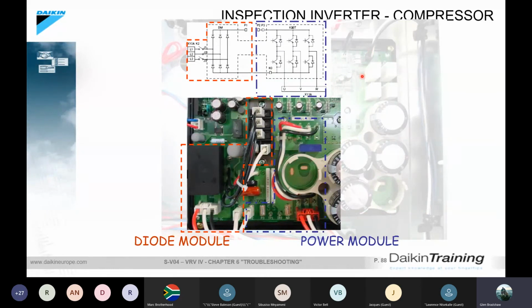Now, the only way that you can effectively change the speed of a motor is by playing with the frequency. And I think if you go back to the old days of standard compressors, many of you may have remembered that you could often select replacement compressors from Tecumseh and things like that, and you would see a chart for 50 and 60 hertz, and you would have noticed that a 60 hertz compressor had a slightly higher output due to its higher speed.